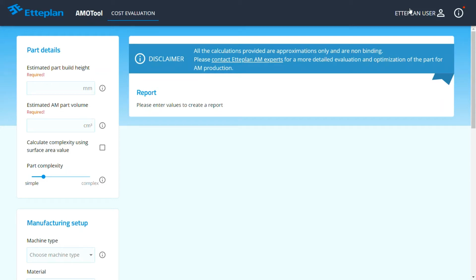Hello and welcome to this instructional video explaining the use of Etteplan's AMOTool. This web-based calculator can be used to estimate the cost of creating metal parts with additive manufacturing and to also evaluate how design modifications that reduce, for example, build volume or build height impact the manufacturing costs.